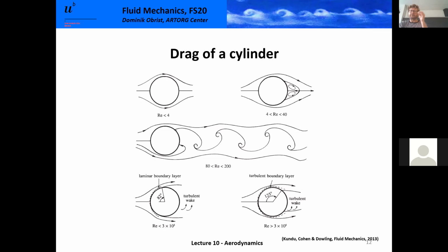In the first place, if we were only to look at friction drag, transitioning from a laminar to a turbulent boundary layer would of course increase the drag, right? Because the turbulent boundary layer usually has a steeper velocity gradient at the wall. Maybe you remember these diagrams where I showed you what a Blasius boundary layer looks like and what the mean velocity profile of a turbulent boundary layer looks like.